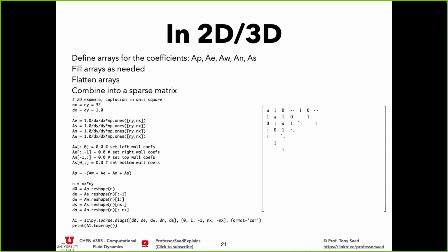There are no variables in the south. There's no array, unlike the coefficient at this point; the next variable is this guy. So we say the east coefficient is 0 because it connects to that guy, and it's 0 times that guy, so it doesn't matter. But when you get to this point, there are no more variables behind it. There are no more grid points, so that's why we trim it at the end. And same thing for the west coefficient. There's no west coefficient here, so we need to cut that off. That's why I cut it at the beginning for the west coefficient. That's the little trick here to do this. But once you accept this and figure it out, it's a piece of cake.